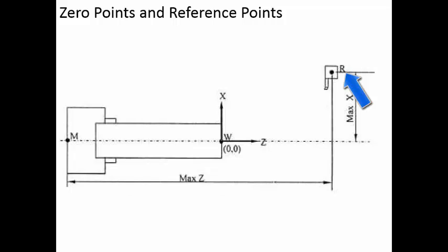Whatever tool changeover is required, or rotation of the tool magazine, all these things will happen when the tool system is at the home position. There the required motions will happen and the appropriate tool will be selected or brought into position. Again the program will continue to machine the required component.